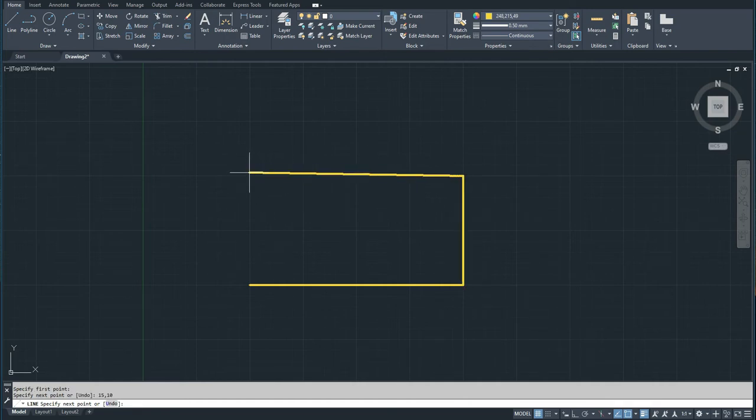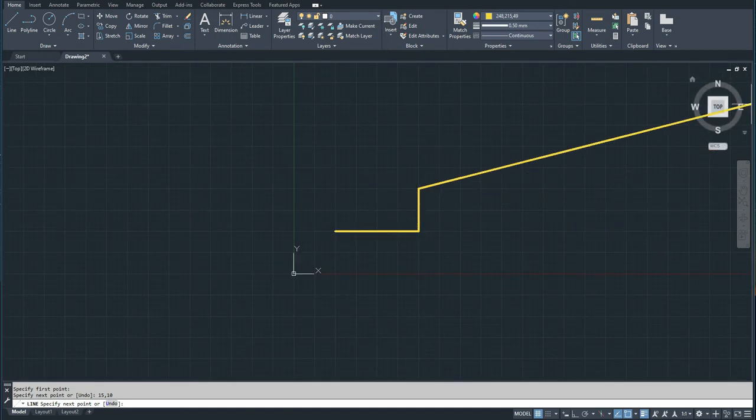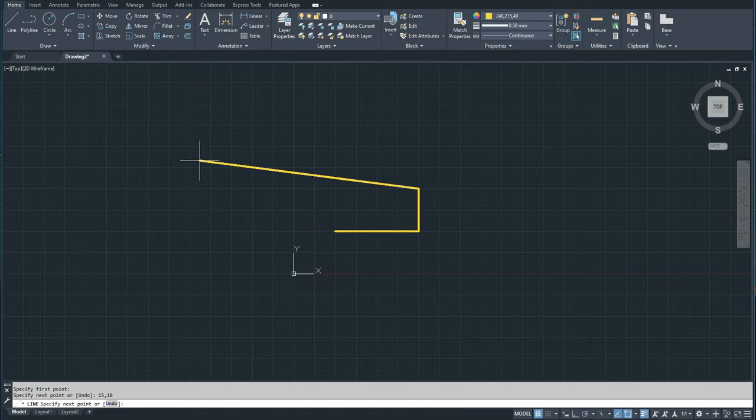Now if I go to this point, okay, now guys, for this point, I will show you. For this point, exactly this point, guys, we have to go from here to here, as we said, it is 5 before, and we'll go from here to here, 5 and 5, which is 10. So in x direction it is 5, and y direction it is 10. So I have to go back to here and select, as I told you, it is 5 in x-axis and it is 10 in y-axis. Now I will get back to this point. It is 5 by 5. Enter.